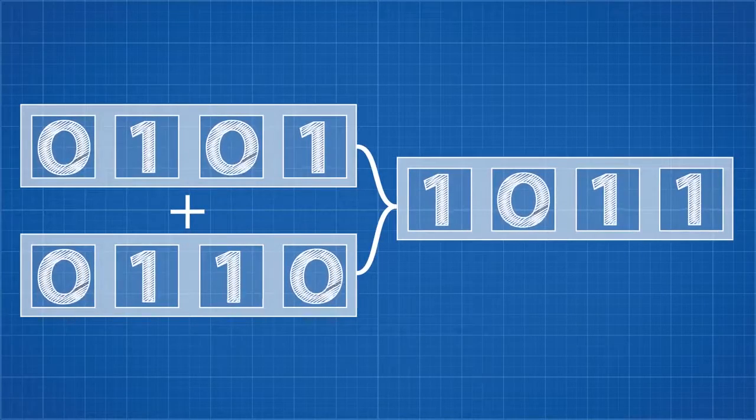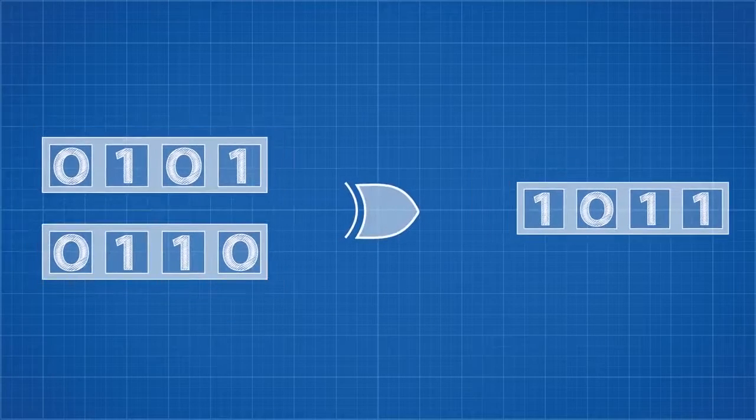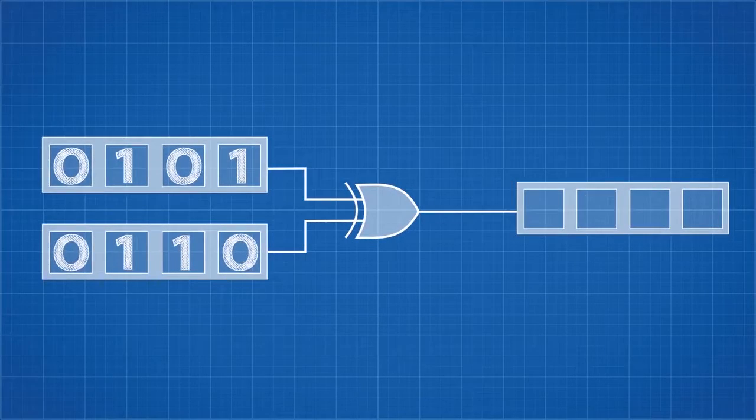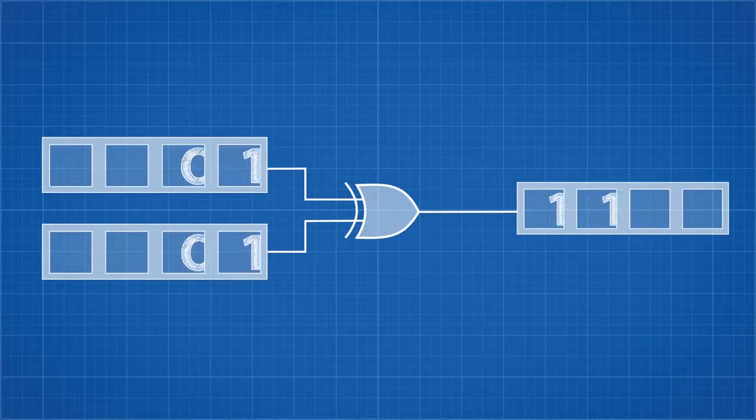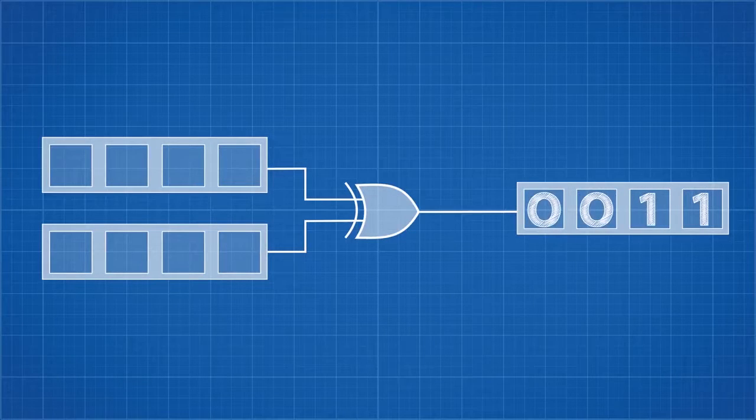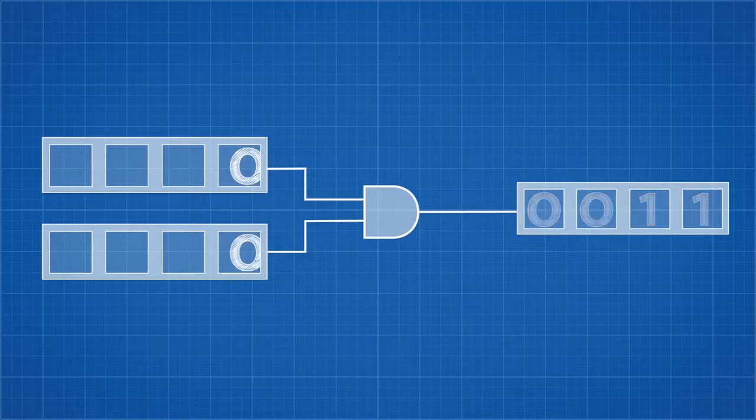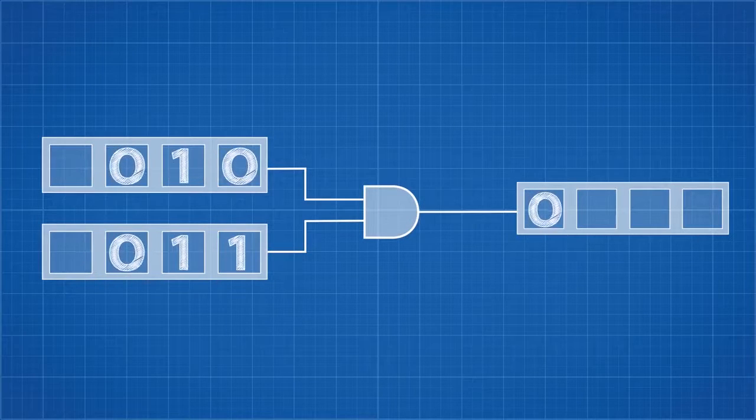The simplest circuit that can do this is a half adder, which contains 2 types of logic gates. These are devices that can modify the binary code. They are built using transistors. The first is the XOR logic gate, which gives a 1 only when one of the inputs is 1. If both are 0 or 1, it gives a 0. The second logic gate is an AND gate, which gives a 0 for everything except when both inputs are 1.